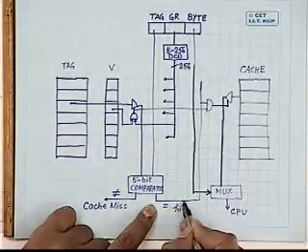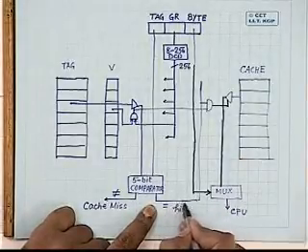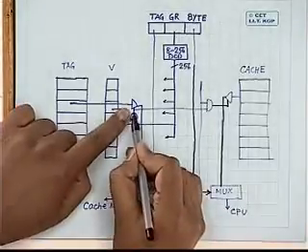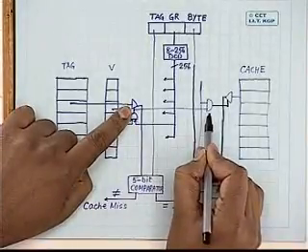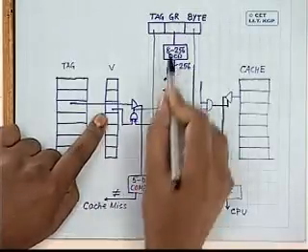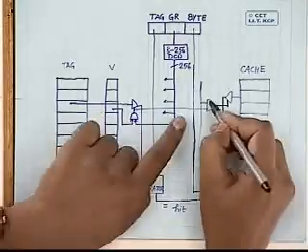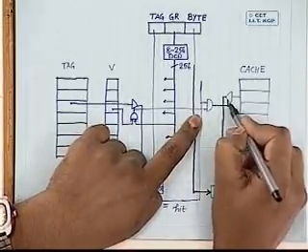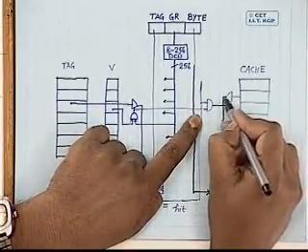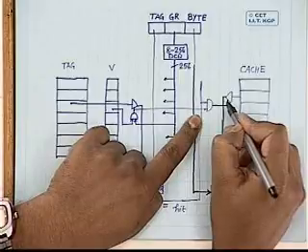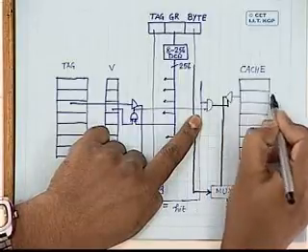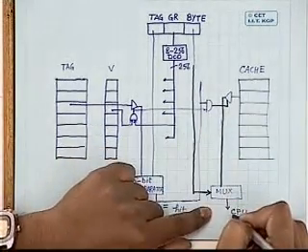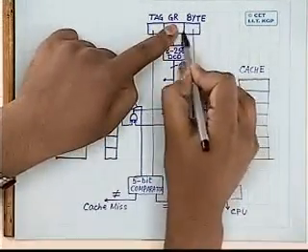So what I am doing is I am ANDing this equality output from the comparator with the output of this AND gate, which is ANDing the valid bit with the decoder output. So only when both these conditions are high, then only I will take out the corresponding cache block again through this buffer. Okay, so here what I get is the entire cache line which contains 8 bytes. Out of these 8 bytes, I select one particular byte by making use of this byte field.